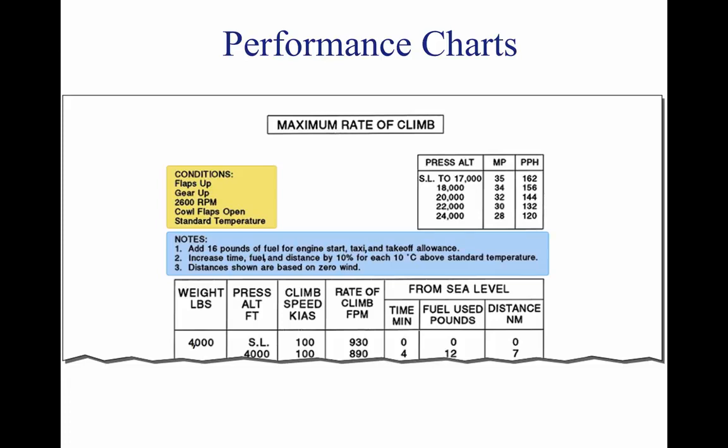By using these performance charts, a pilot can determine the runway length needed to take off and land, the amount of fuel to be used during flight, and the time required to arrive at the destination. It is important to remember that the data from the charts will not be accurate if the aircraft is not in good working order or when operating under adverse conditions. Compute the performance of the aircraft prior to every flight, as every flight is different.